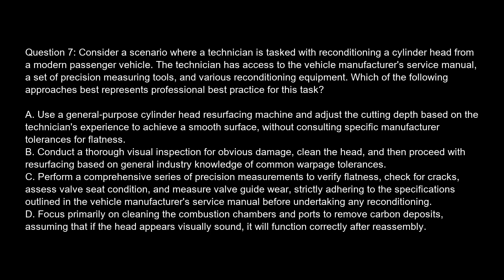Option C. Perform a comprehensive series of precision measurements to verify flatness, check for cracks, assess valve seat condition, and measure valve guide wear, strictly adhering to the specifications outlined in the vehicle manufacturer's service manual before undertaking any reconditioning. Option D. Focus primarily on cleaning the combustion chambers and ports to remove carbon deposits, assuming that if the head appears visually sound, it will function correctly after reassembly.